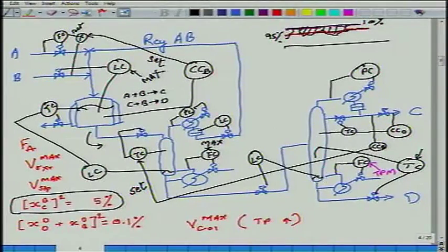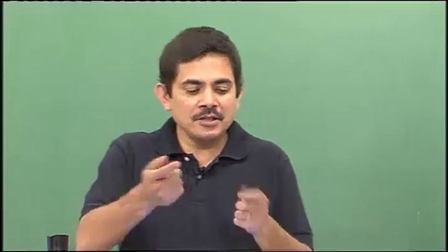So as you are pulling in more feed from the reactor, level of the reactor goes down. You start pulling in more B. The level controller starts pulling in more B. Ratio controller makes sure that more A gets pulled in. If there is any mismatch, the composition controller takes care of that.